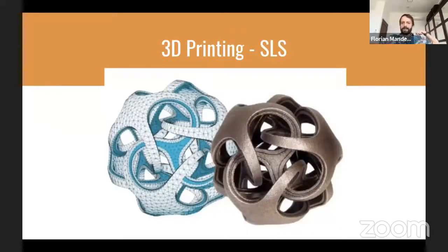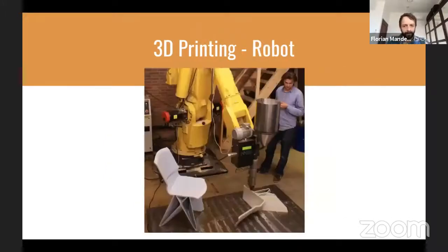For everyone that's SLS, I just put this picture here to show you how you can use SLS to print basically in the air. So you can create more complex parts, and you can use different materials, because the material you don't use for the process supports the material you need, or where it hardens. So after you take it out from the powder bed or from the resin, the material you didn't use will just come off, and that's where you have then the remaining part.